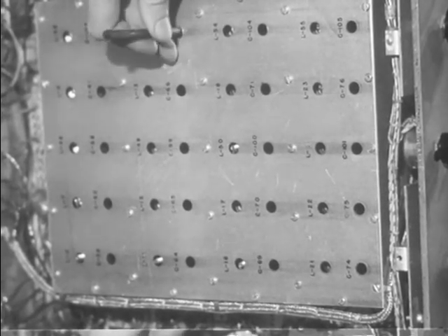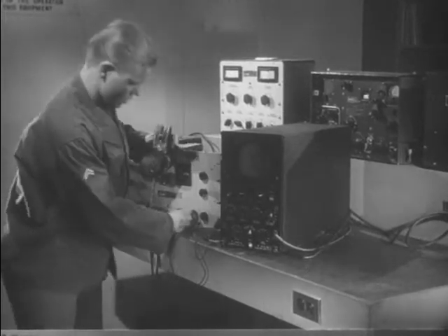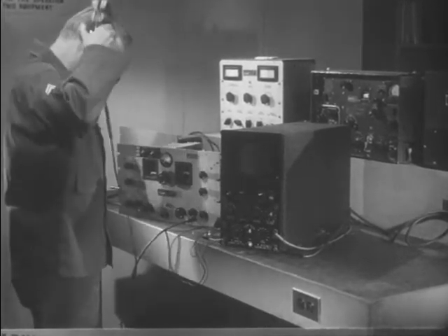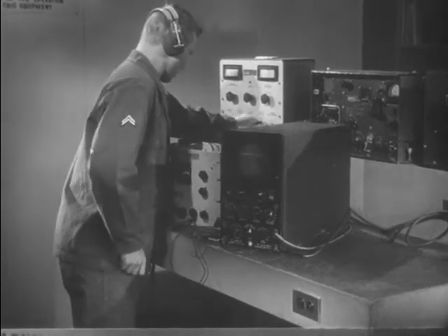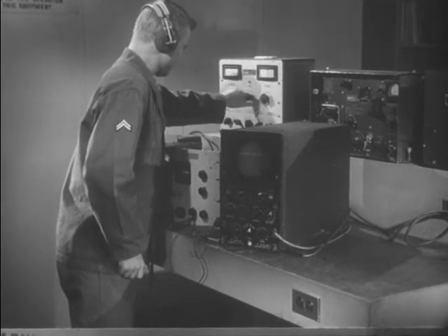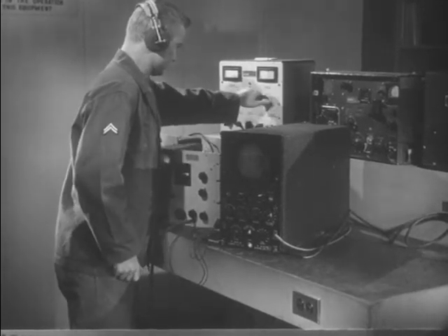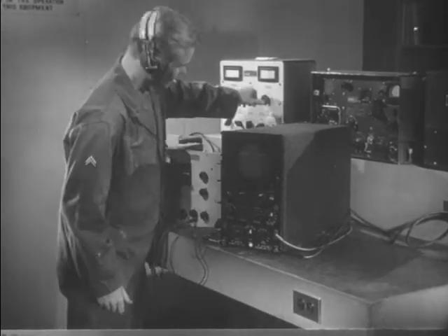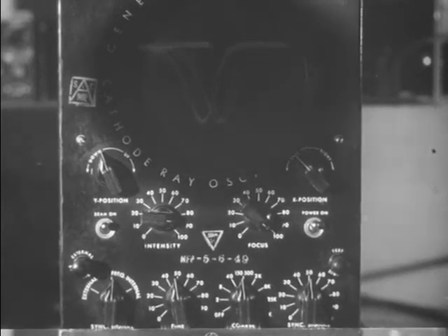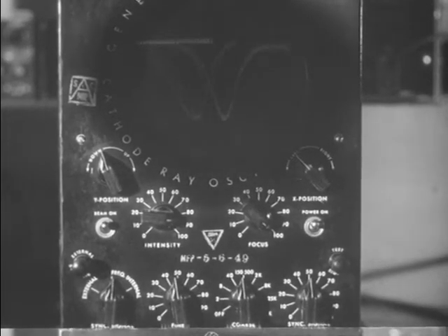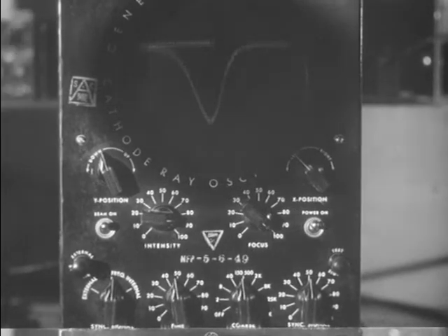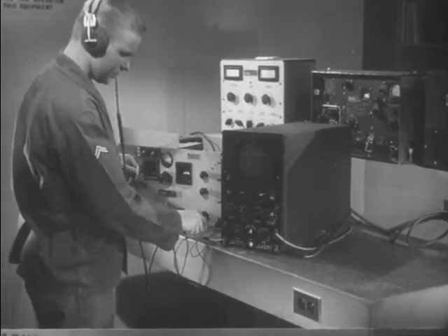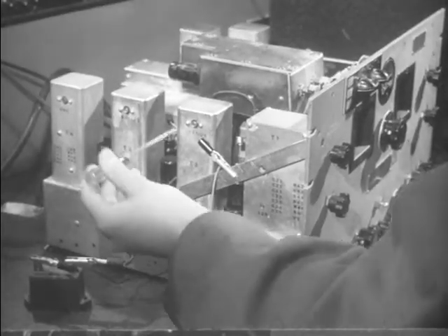For certain types of work, particularly that involving waveforms, the Cathode Ray Oscilloscope is used in place of the output meter. Here, the signal generator frequency is varied at a certain rate over a band that extends 5 kilocycles on either side of the IF frequency. The oscilloscope sweep circuit is synchronized with the signal generator frequency sweep and produces a curve which is a reproduction of the selectivity curve of the amplifier under test. This is very helpful in tuning the IF amplifiers to pass a certain band of frequencies and exclude all others.